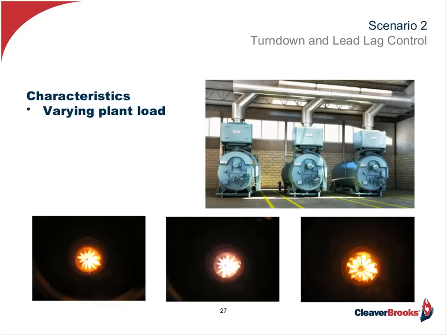We have to really understand the load, and this is where so many engineers and so many facility managers make a mistake. They don't fully understand how this load operates, if you will. So it could be that we may have to go not just with a 10-to-1 turn down burner, but also multiple units to be able to catch these loads at the various levels. And then to improve the overall efficiency, we may even be looking at adding economizers to these boilers.